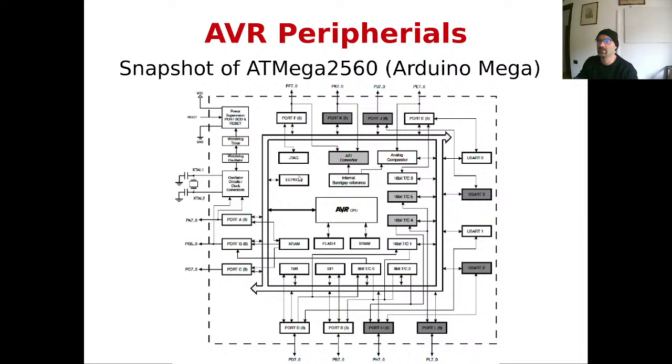You have an EEPROM, which is something different from the flash. The flash is used to store the program. The EEPROM is like a non-volatile memory, which is accessible by the program itself. Once programmed, the AVR doesn't let the code alter the program memory. This is because it's a hardware architecture. This is a safety thing, also a performance thing, that is used in microcontrollers to prevent malicious code from altering the content of the program, so basically to prevent viruses.